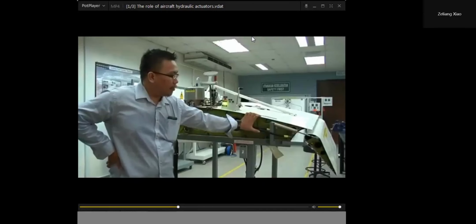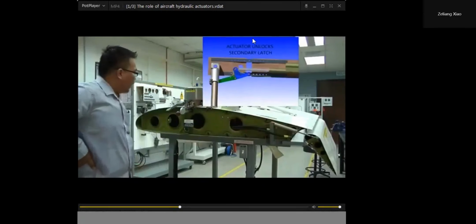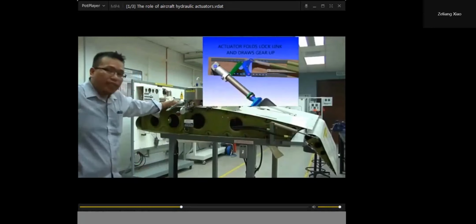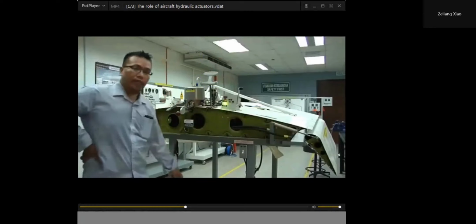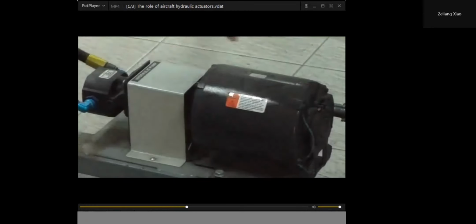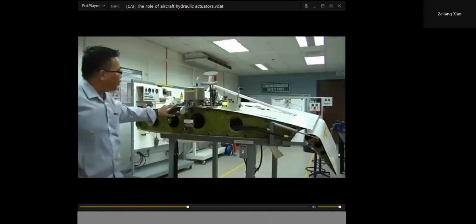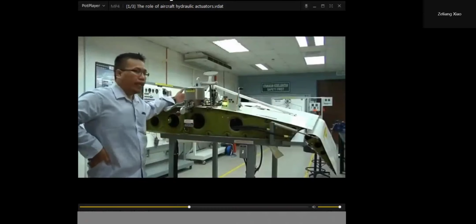Then I will take a landing gear hydraulic system, which is a good trainer. As you can see, it has two hydraulic actuators, which are used for the flap and the landing gear. This is a basic hydraulic powered system. Consider the pump underneath, which drives the pressurized liquid upwards to the filter, and we have a valve side here and the reservoir.